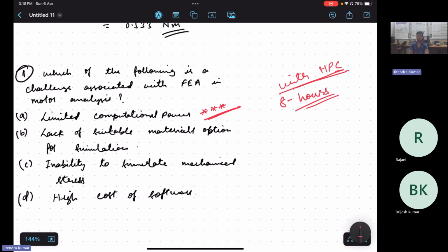Generally, the computation time of any FEA analysis you perform, the finer the mesh, the higher the time it will take. Higher the accuracy, yes, sir. You can select a finer mesh also. That is what I am saying, there are three types of meshes, a very dense mesh, if you have more time. In 3D, what is happening is that your mesh also protrudes along the z-axis, right? Yes, sir. That way, your mesh is going to increase for 3D analysis.